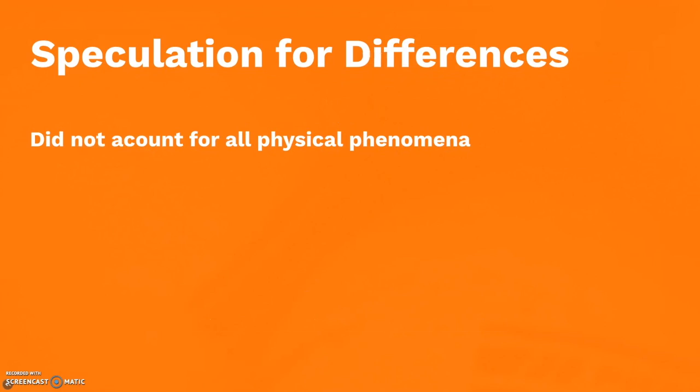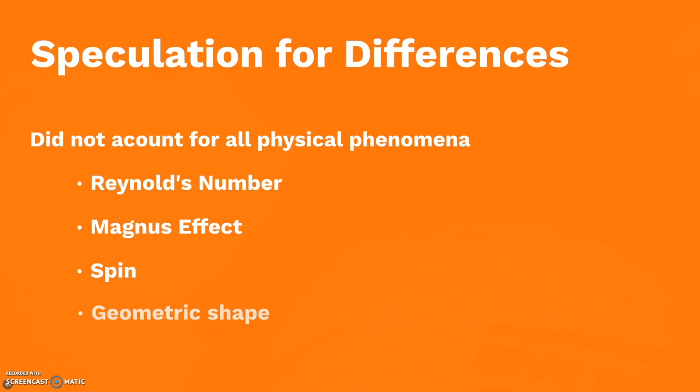Why is this the case? The larger pressure difference and turbulence was not expected with square dimples. It is possible that our understanding of these results is getting abstracted because we are not taking into account other factors in aerodynamics, such as Reynolds number, Magnus effect, and the assumptions we made when we modeled the simulation. The geometric shape of the square dimple doesn't allow for a tight flow of air. Again, this is just speculation. We won't have a conclusive reason for this result until we conduct further investigation.